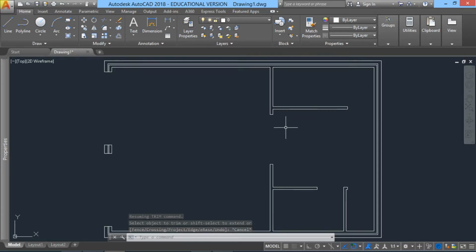On this stage, for the building which I'm drawing, I need to cut 4 more openings for the windows. For the utility room, the dimension for the window is 600 and it's about 900 from the external wall.